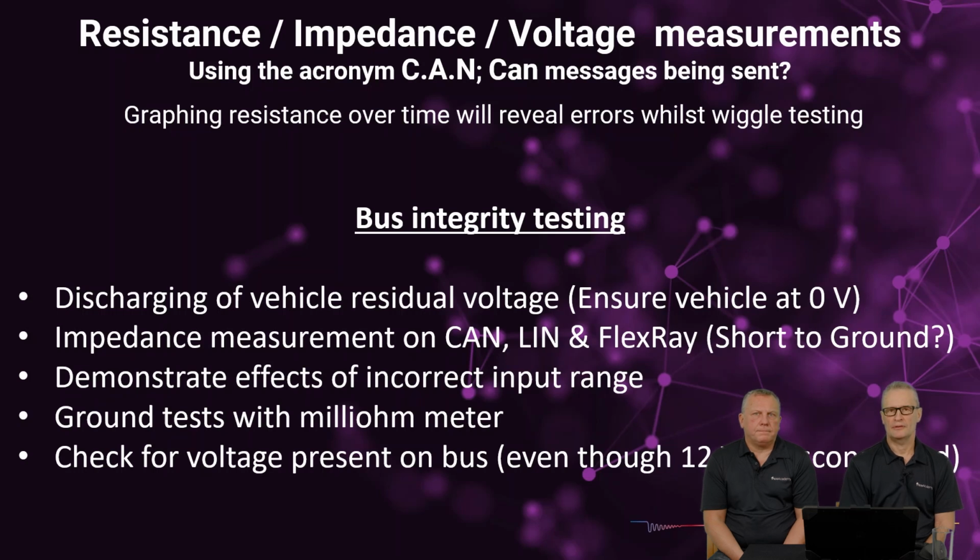It comes down to aftermarket devices maybe, or devices that are self-powered. I certainly had some very bad experiences of immobilizers that chose to manipulate the CAN to prevent the vehicle from operating in the event of an attempted theft. What a heartache that can be. Yeah, trackers. There are devices where people don't pay their bill for their car that stop them starting. All of those have a supplementary battery, which can, as we'll demonstrate, play havoc on the networks.